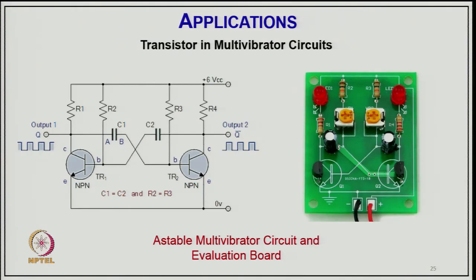And the third is the astable multivibrator, from which you can get a frequency decided by your RC network. When you want a variable frequency of output, you can attain that from this, and you do not have to give any input. It is self-oscillating at a given frequency, which you decide by the design of these components, like the RC components here.